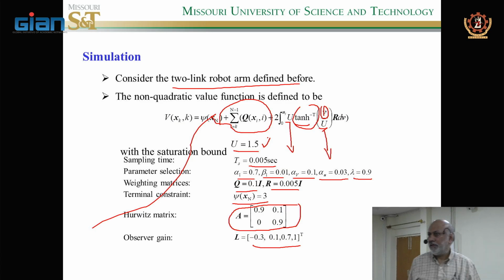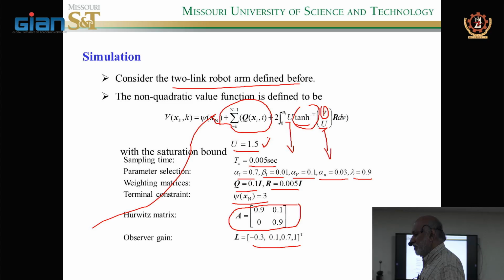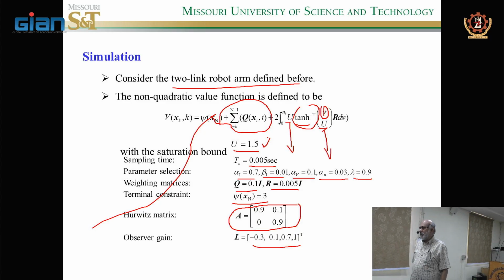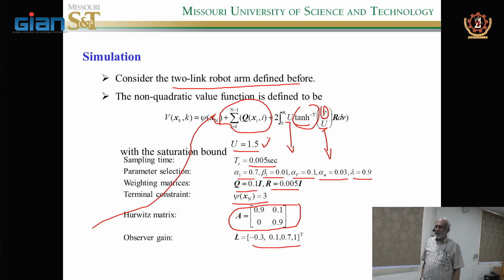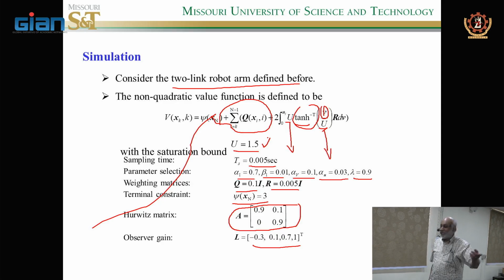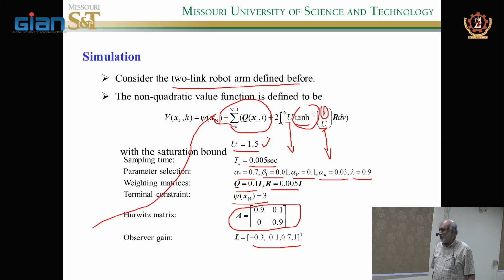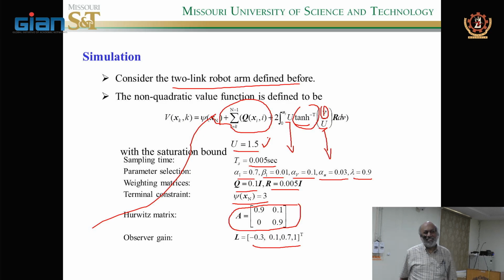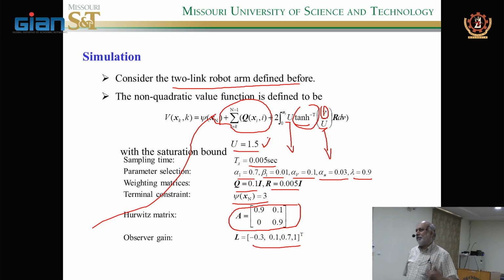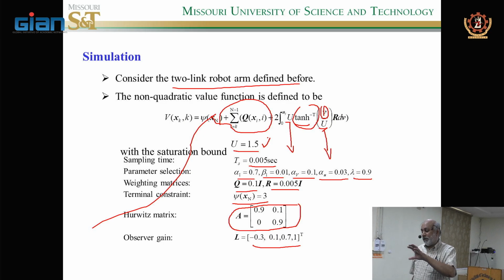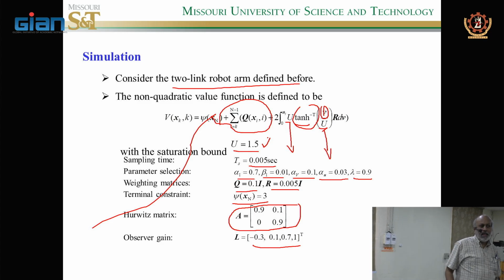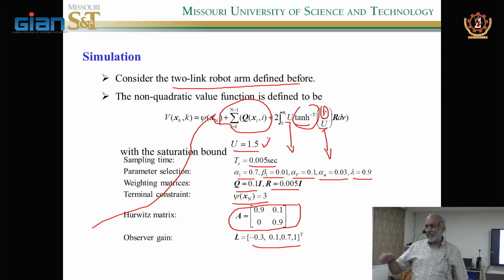Even for the simple state feedback controller, when you are doing regulation, the same control will not work for tracking, because there will be a steady state error. You have to modify u equals minus k. Right, that's what I want them to tell me, why it doesn't work. It doesn't matter whether linear or nonlinear. You're right. She was asking why it works for tracking, and controllability doesn't matter, but not in the design. That's why I want that to come back. What is that extra term?